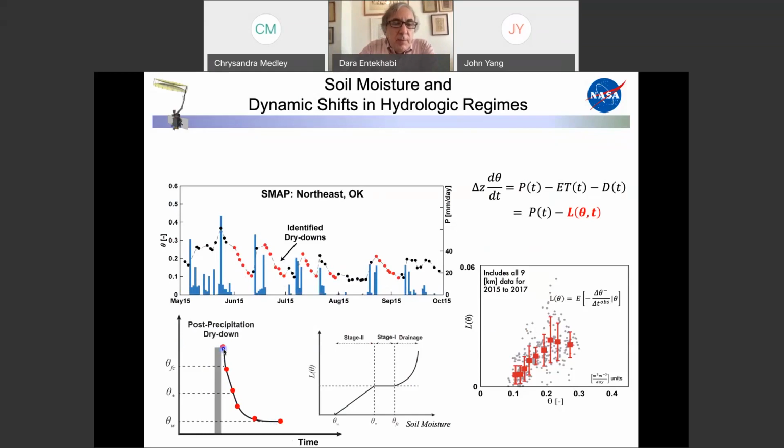And very quickly, soil moisture is reduced to this level, which is called the field capacity. It's an old soil physics definition. It's a soil moisture level below which gravity is not adequate enough force to draw water out of a soil column. So it's an energetic definition.